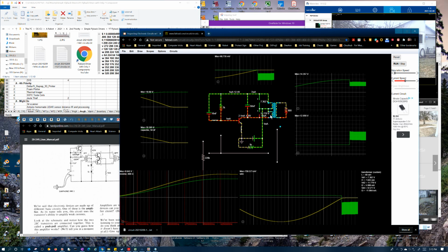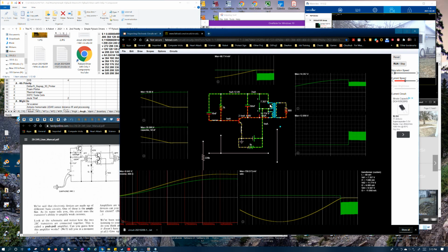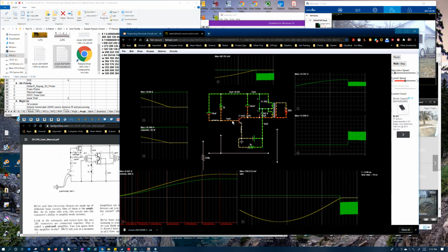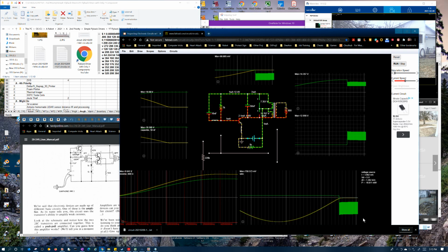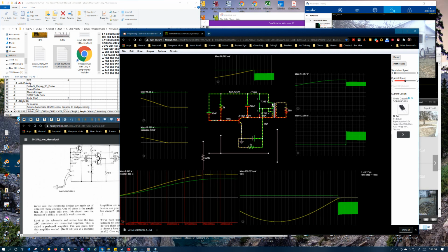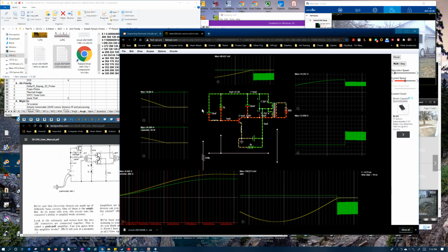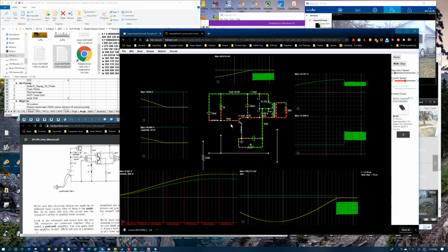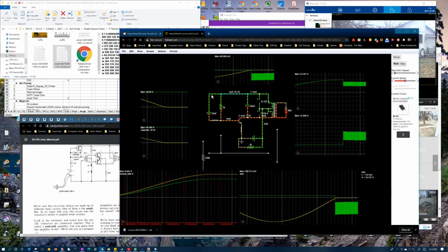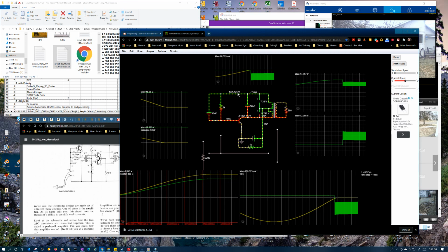But as this field collapses, it should definitely generate a voltage of opposite polarity. That should be taking our voltage below zero, which in fact is showing over here, because as this voltage reduces, remember this capacitor still has 18 volts across it, so this is actually forcing this negative terminal down below ground, as this voltage falls.